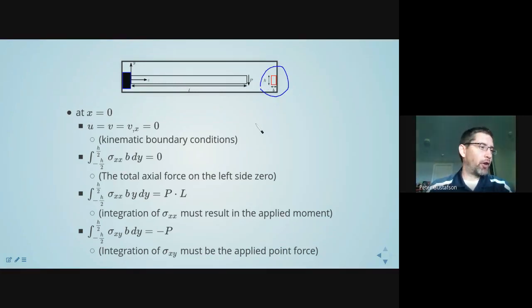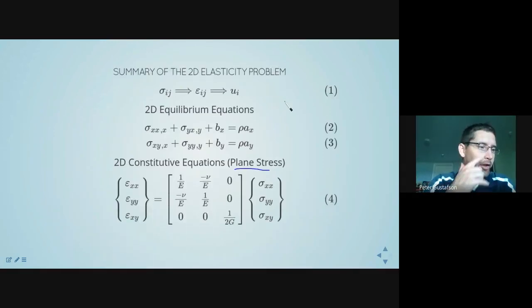the cross-sectional area, and Nicole had asked, if it's deep, if it's long into the depth of the plane, is that plane strain? Generally, yes. If it's thin in that direction, it's generally going to be considered to be plane stress. So as a general rule, if we're going to treat this as one or the other, I'm going to choose plane stress since it's relatively thin.